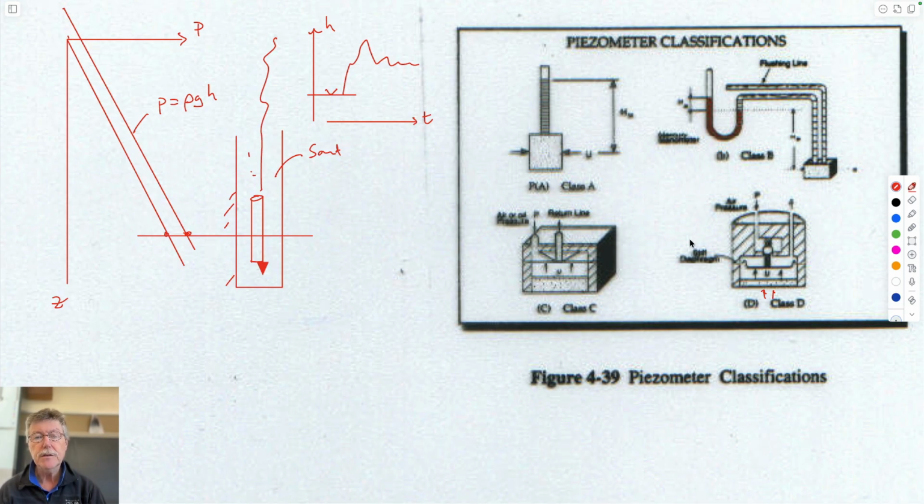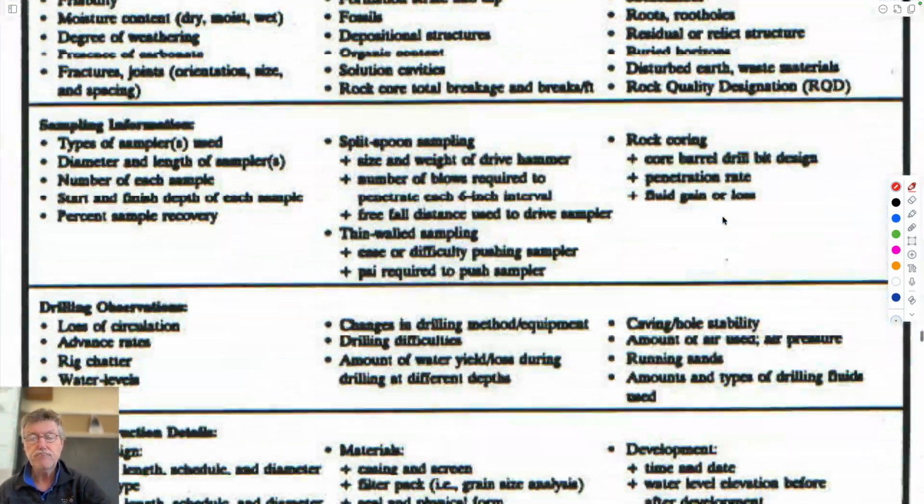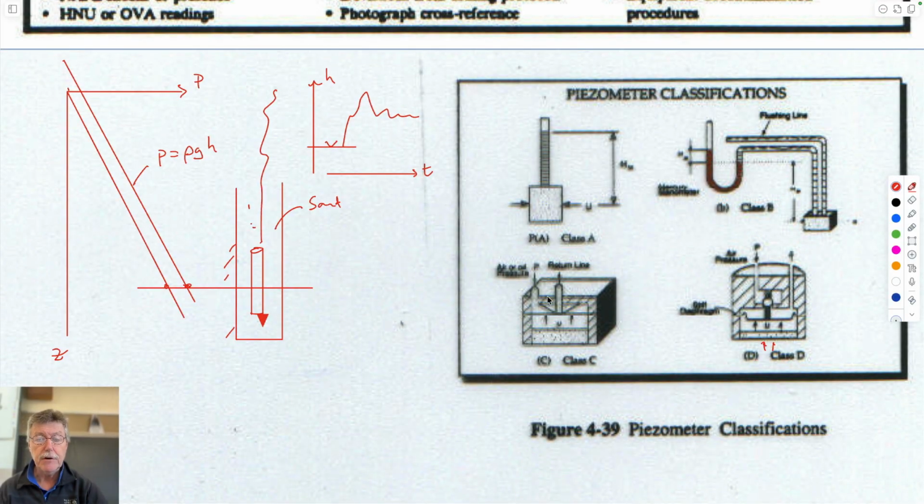This is just a manometer, as you'd know, and this is a representation of a standpipe piezometer, just like the one we talked about here. And I think this is representing a pressure transducer, which is just a membrane pushed against by the water on the outside. It deflects, and you measure the deflection of this membrane with a little strain gauge. That deflection then is calibrated with the pressure underground.